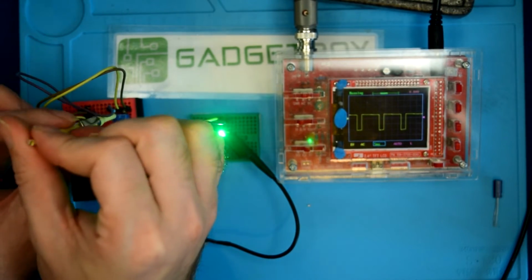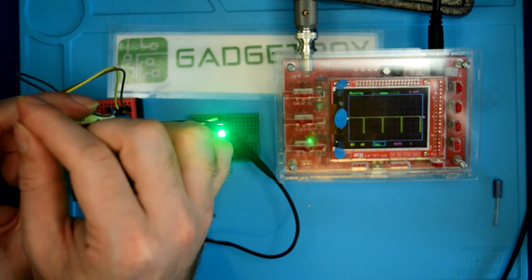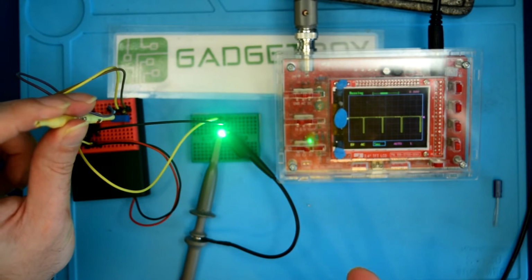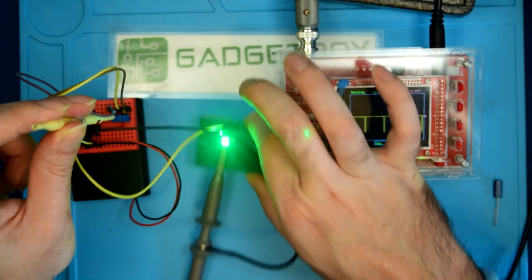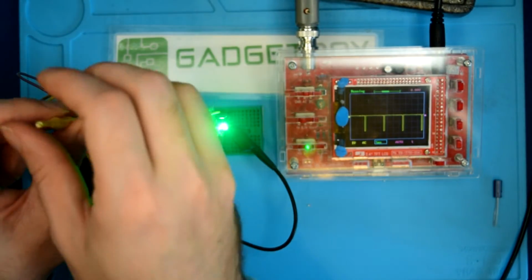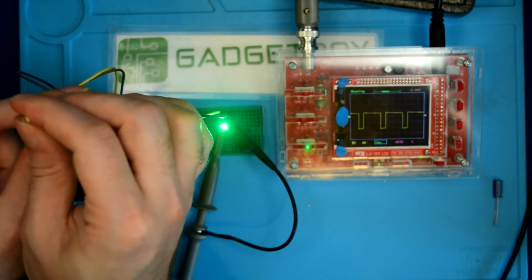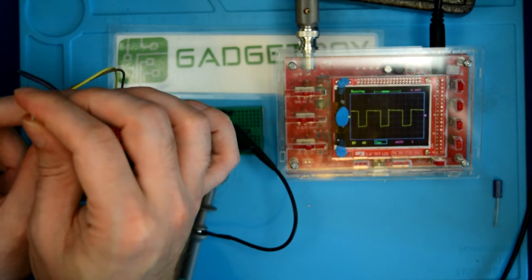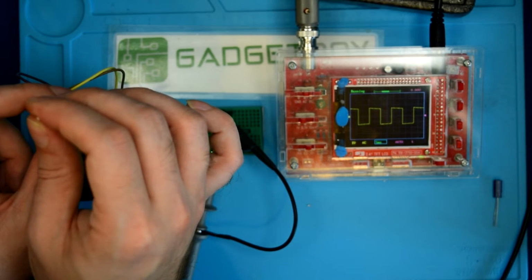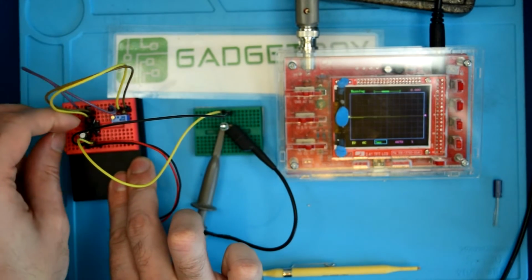Now if we take that duty cycle and increase it, let's bring it up into the 90% range. There we go. You'll notice the shimmer isn't as pronounced, but if I wiggle it, we'll still get a little bit of shimmer. But that's why pulse width modulating LEDs in a filming situation can be a little challenging. So let's bring this back to about 50% again. There we go.